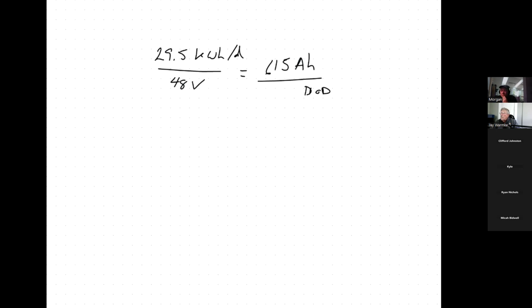Let's see, it says on PV watts, solar radiation was 4.43. Is that the equivalent of 4.43 hours of insolation per day? Yeah. Because the question was, it says 4.43 kilowatt hours per square meter per day.